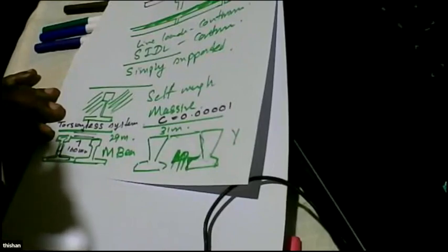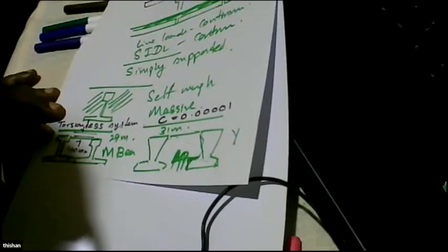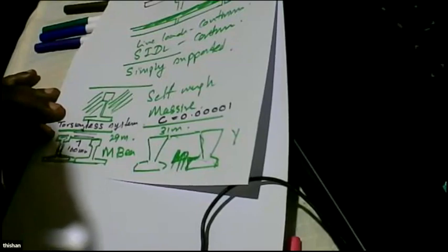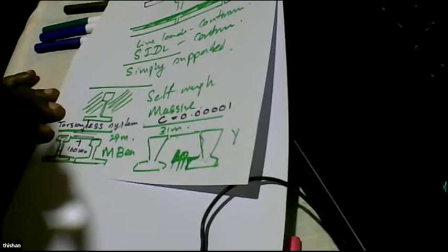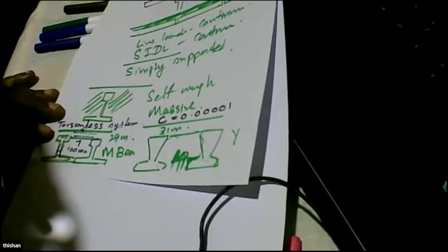So these days I like to adjust the supports if at all possible, so that the skewness can be reduced. Rather than having a huge bridge as one bridge, you can easily stagger the supports and have it as 2 or 3 parallel bridges. That way, you can minimize the effect of skew. But if you really want to go for a massive bridge, let's say a 6-lane highway, where the supports are not perpendicular to the road, so supports are at an angle.